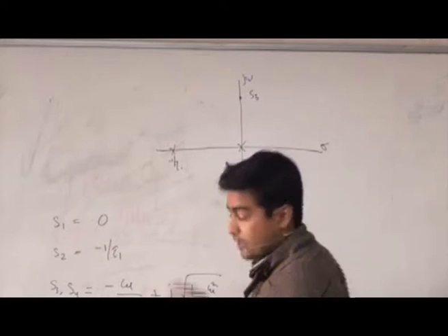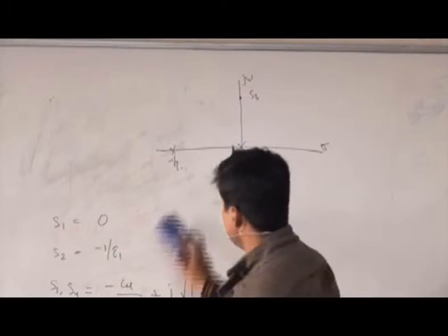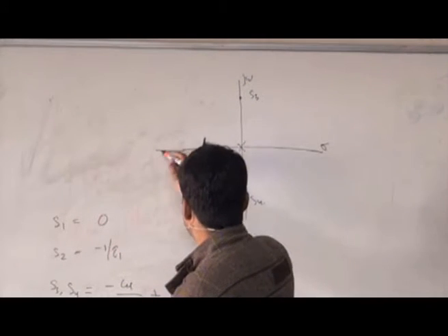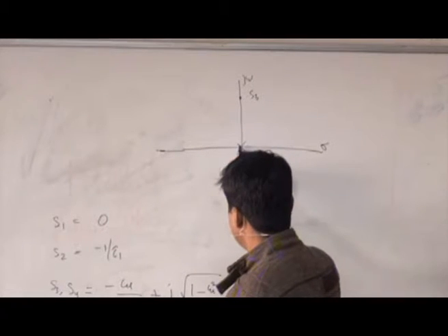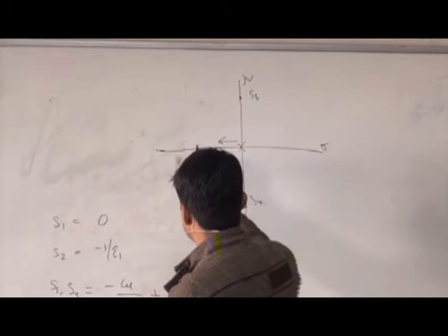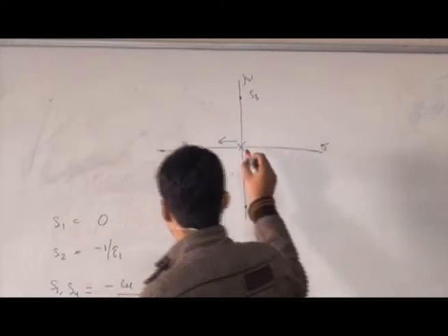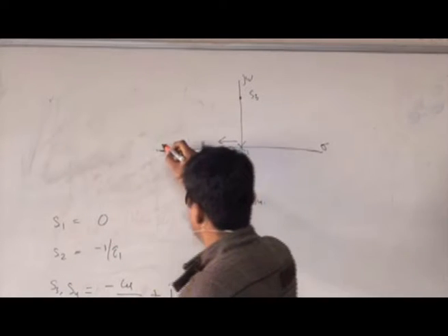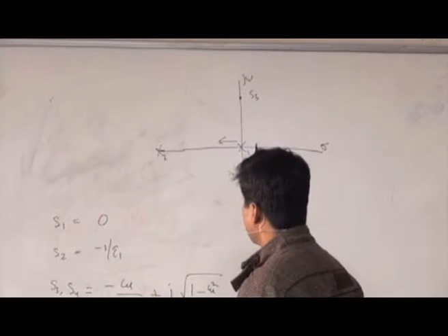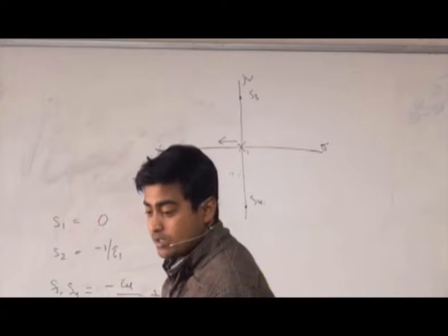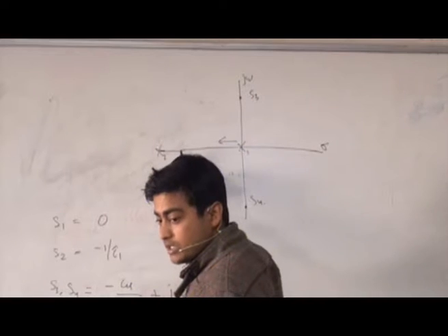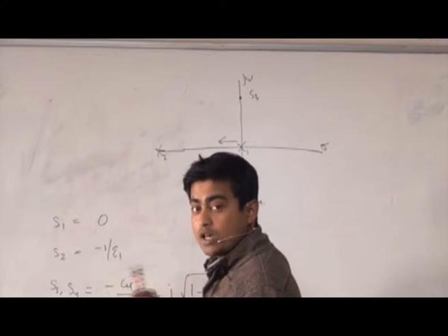Let's say if I remove this pole, now I have only one pole here, and I start moving this pole in the negative direction. Now I would say cross 1, the new position, cross 2. This is the same pole, only one pole. So what observations will you see in the response of the system? You will notice that as you move farther from the imaginary axis, your response will start becoming faster.